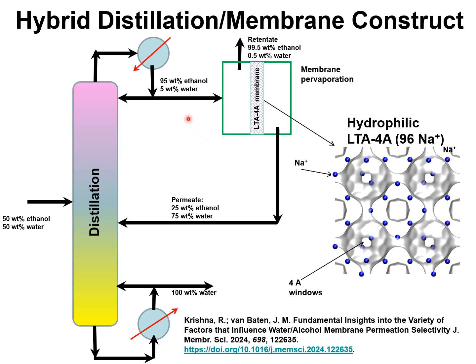Due to the formation of the ethanol-water azeotrope, the production of ethanol with purities in excess of 95% is impossible in normal distillation operations and requires the use of azeotropic and extractive distillation and the use of entrainers such as cyclohexane and benzene.